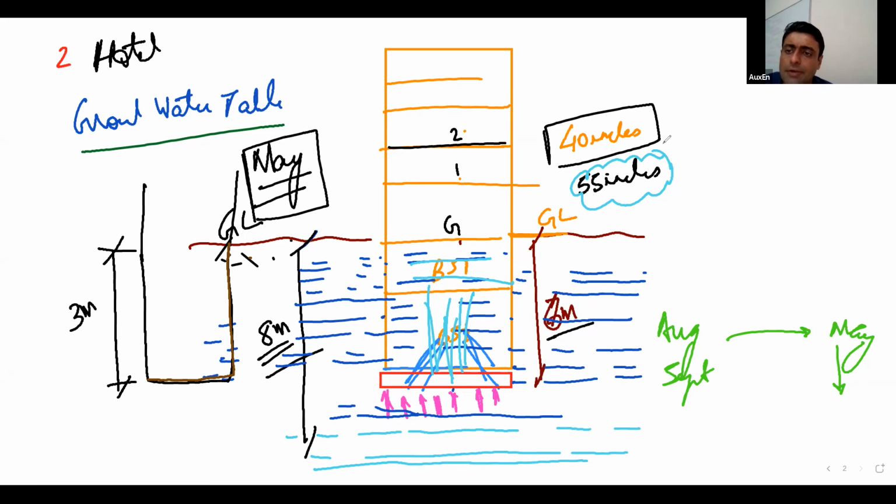This is the same thing that Prasad sir is writing. He is saying that groundwater table rises in the monsoon period, and therefore we should consider some safety margins. This is the exact suggestion that I would also have. Generally, all your reports would indicate the period during which this testing was carried out. So it is extremely important as a designer that you understand the seasonal variations possible.